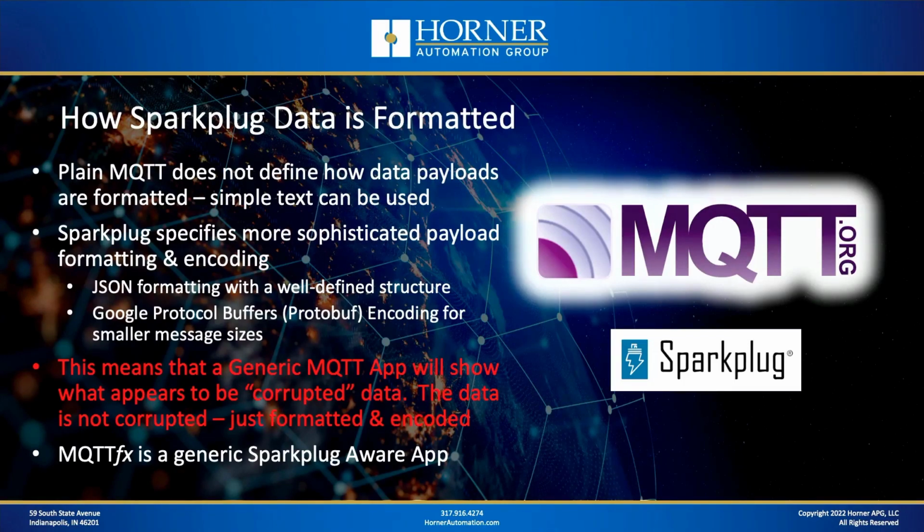The problem with that, because there's not much definition, is that there's also no definition not only for the format the data goes in, but what data format is it in? Is it integer, double integer, floating point? Is it ASCII text? What is it? So with Sparkplug, all that is defined, again, to help with interoperability. That's a really huge deal.